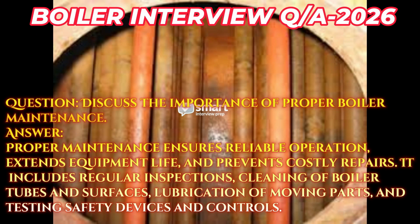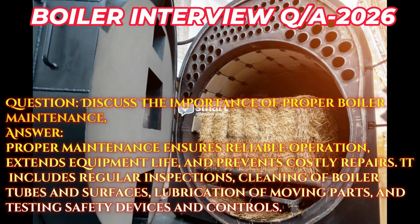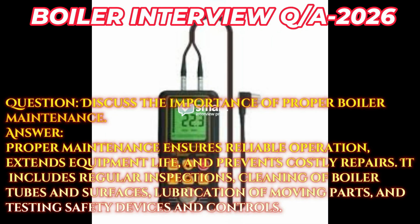Question: discuss the importance of proper boiler maintenance. Answer: proper maintenance ensures reliable operation, extends equipment life, and prevents costly repairs. It includes regular inspections, cleaning of boiler tubes and surfaces, lubrication of moving parts, and testing safety devices and controls.